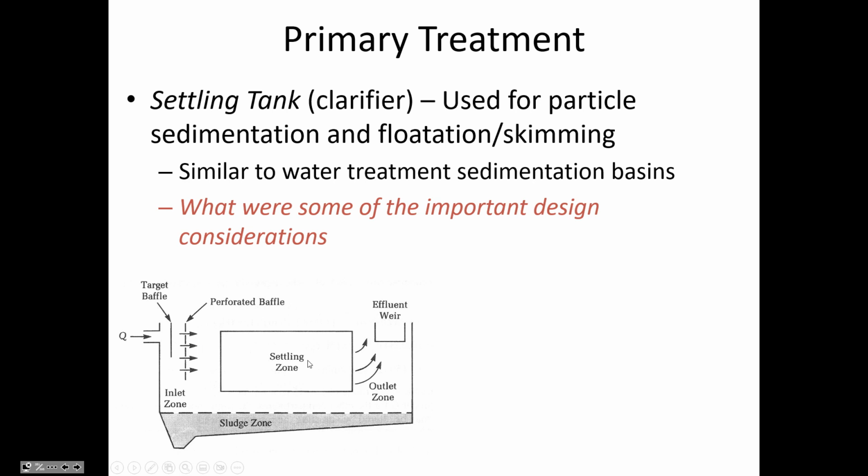And then the other way that we make that happen is by distributing the outflow over a large cross-sectional area. Because remember the continuity equation, which says the flow rate Q is the velocity times the area: if you want to have a low velocity as the water exits the settling zone, then you need to have a large cross-sectional area. So small v, large A to get the flow rate that's needed. And so the way that we maximize area is with those V-notched weirs in the launder.